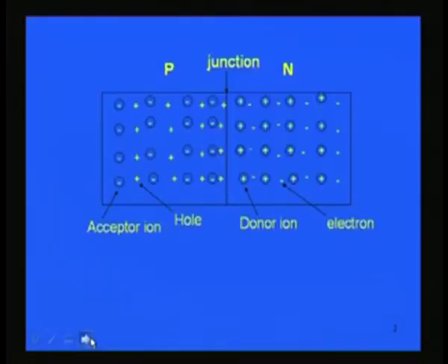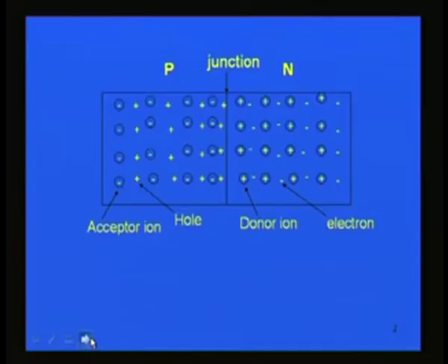When you have p and n type semiconductors combined together by some appropriate scheme like ion implantation or diffusion, this process is not mechanical, mind it, so as not to disturb the crystalline structure of the silicon or germanium semiconductor, which is the base material. A properly formed p-n junction will have p-type on one side and n-type on the other side.